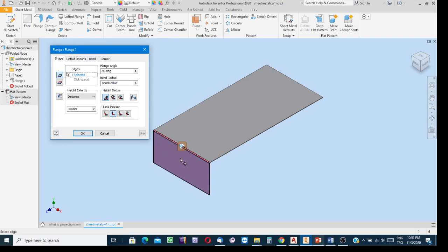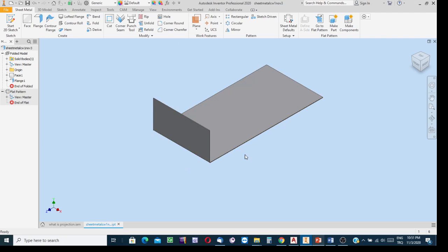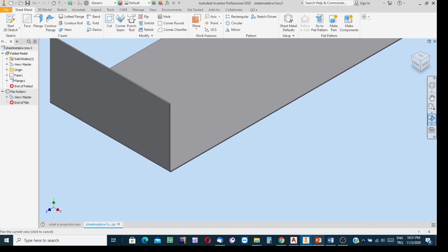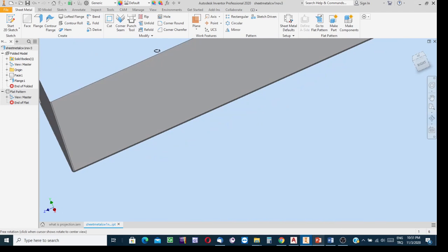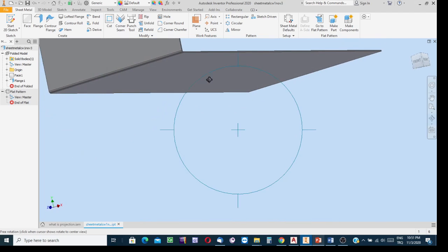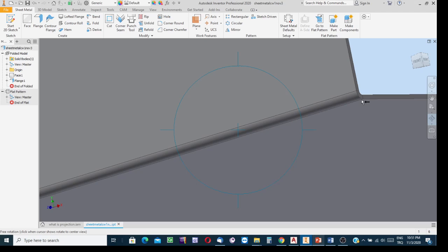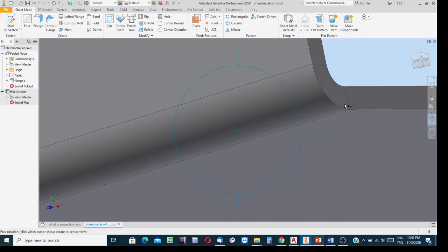If the direction of the bended part is to be reversed, here is the flip-flop facility. Click on this and then have the bended part extended in the up direction: down, up. Yes. And then say OK. And here one more time highlight that we have a transition part, this round, and Inventor created this round at the background, calculating the bending allowance.